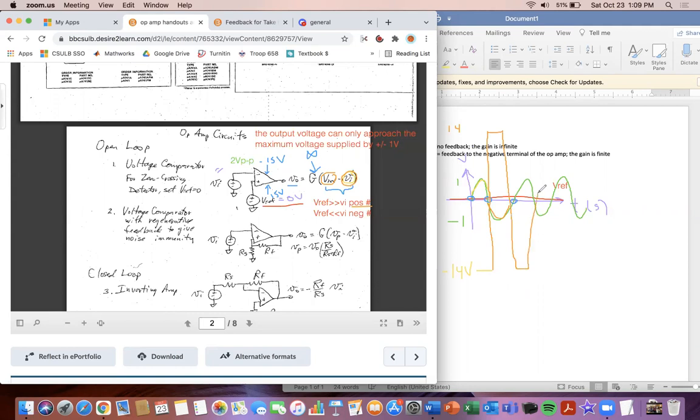With the square wave, one important factor to consider is the slew rate. The slew rate is the time it takes for the output voltage to change. That was one thing Dr. Ari mentioned. So it's not a straight square wave as your output. It has a little bit of a slope to it, just a tiny slope, because it takes a little time for the output to change in response. That's the effect a slew rate will cause, if he brings that up.